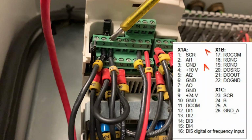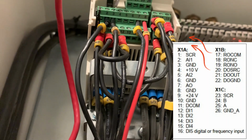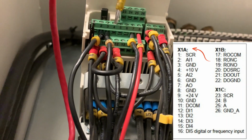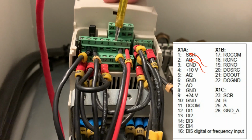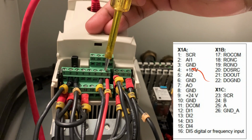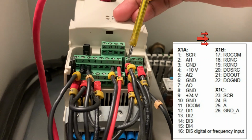Terminal 2 and terminal 3 are for analog input 1: this is the analog input 1 and this is the ground for analog input 1. The fourth is a 10 volt supply, 5 is analog input 2 and 6 is the ground for analog input 2, 7 is analog output and 8 is the ground for the analog output. Now 17, 18, 19, this is the relay.